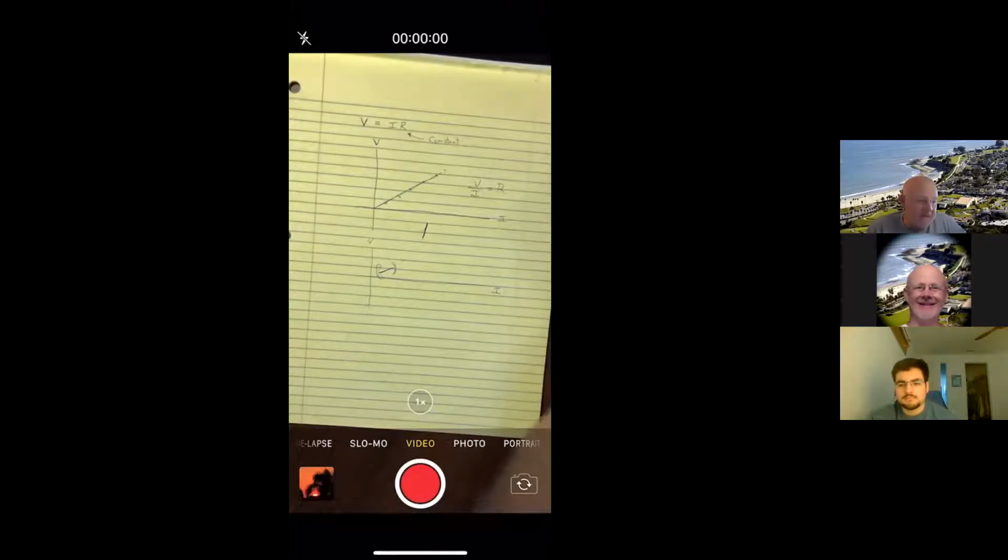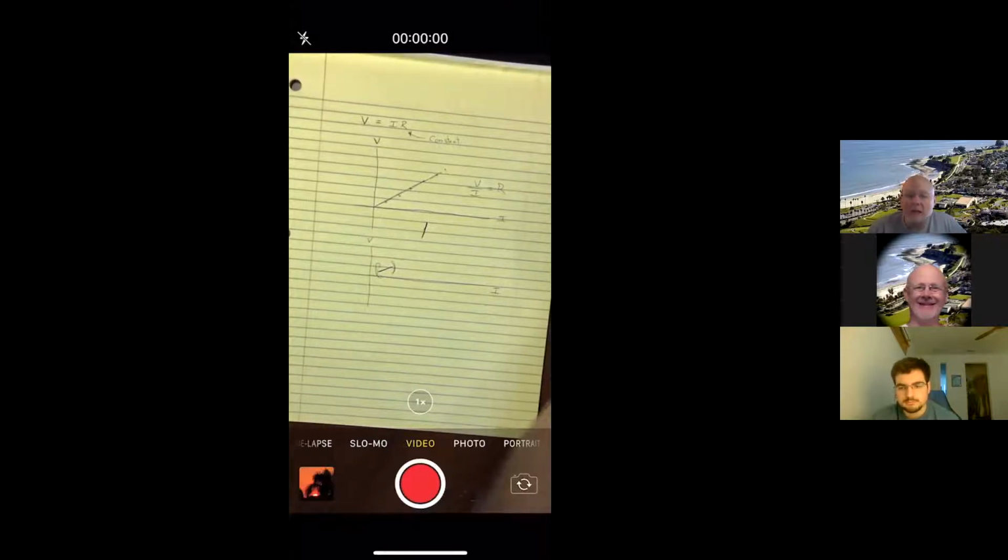If you took a brand new set of them, you wouldn't have half of them below and half of them above. You do get most of them below, because what happens with time is they get abused with heat and then they start to rise in their resistance. And so they do take a little bit of that into effect by deliberately trying to shoot so that the average they produce is lower than their markings. And with time, they will become a little higher than their average. Okay. And so they'll stay within that 10% range for their lifetime. That makes sense. But we do have some that are above. So, in my case, I would say it's just coincidental.